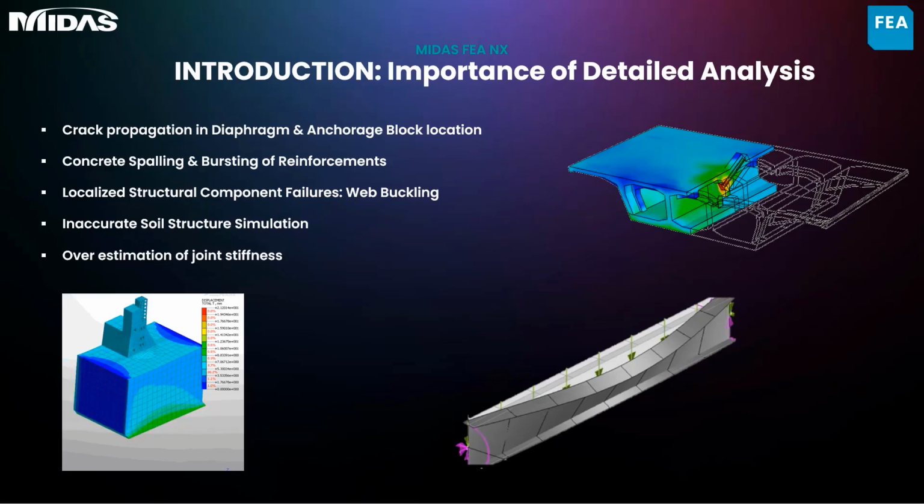So in steel composite bridges, we model the steel I girders as beams in most cases. During early construction, where the slab is not activated, the web tends to buckle under wet concrete loads and often causes failure due to insufficient transverse stiffness. Now, this scenario can be captured only in plate or solid models and cannot be diagnosed using beam or truss models.